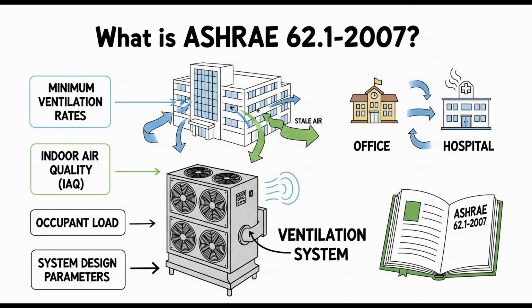Which could save energy, right? Heating and cooling all that outside air costs money. Exactly. Energy savings is often a major driver for using the IAQ procedure, but it requires a lot more design effort, detailed knowledge of contaminants, and often ongoing monitoring and validation to prove it's actually working as designed. And you mentioned subjective testing, people sniffing the air. Yeah. Appendix B mentions that perceived acceptability can sometimes be evaluated using panels of people.